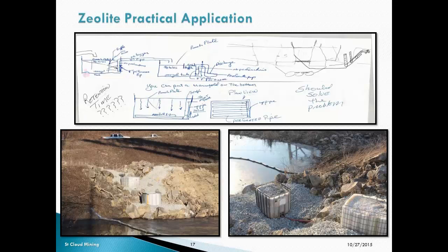The question is, how do you get something from an idea into a process? And TIFF gave me the original napkin on which they sketched out the original thoughts of how you make a treatment process. We ultimately tried it a couple different ways. One is the simple way of taking the zeolites as it arrives in a super bag, putting it in a cage that you'd normally hold large containers of chemicals in to give it structure, and then run the water through it in a downflow mode on a very simple system.